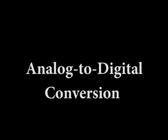Analog to digital conversion. Analog to digital conversion is the process of converting the output of the sample and hold circuit to a series of binary codes that represent the amplitude of the analog input at each of the sample times. The sample and hold process keeps the amplitude of the analog input signal constant between sample pulses.